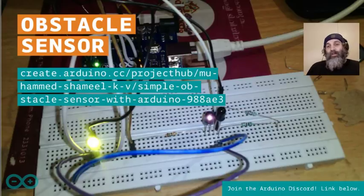There are some other projects in Project Hub that I recommend you check, for example, examples on how to use photodiodes or phototransistors to read the human pulse, where instead of sending infrared light, you use a normal red light, and you listen to the echo of what is responding from the finger, because the blood flowing through our finger reflects red light. So you can use that trick as a way to measure the heartbeat to be precise.